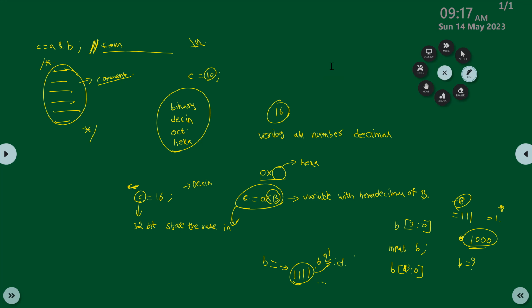If you want to get that specific operation which you pasted in the chart, we require case statements with the mux. Especially you cannot represent... No, you can use the case statement. Okay, but in the conversion, you cannot decide whether a mux will be instantiated or other gates will be instantiated. That is completely the tool's decision. You just have to write your requirement.